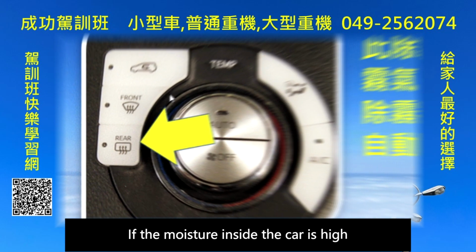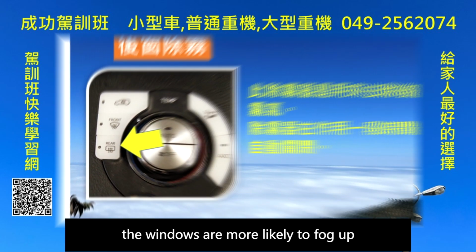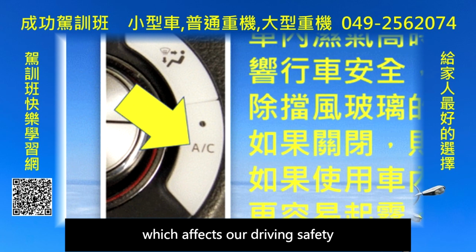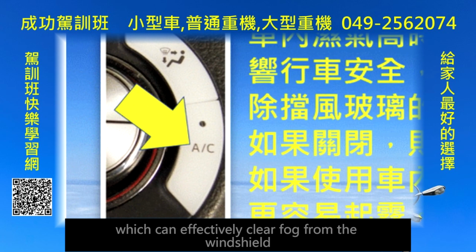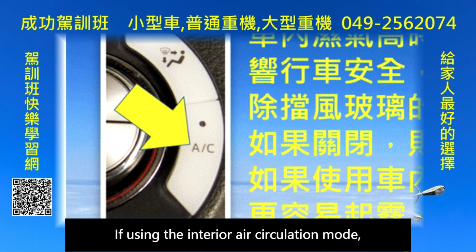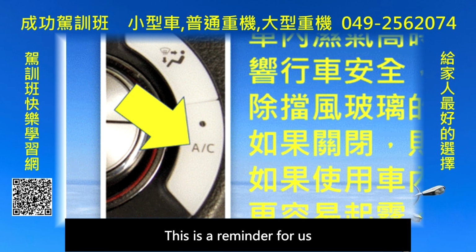If the moisture inside the car is high, the windows are more likely to fog up, which affects our driving safety. So press the AC switch, which can effectively clear fog from the windshield. If it's turned off, the windows may fog up easily. If using the interior air circulation mode, the windows are more likely to fog up. This is a reminder for us.